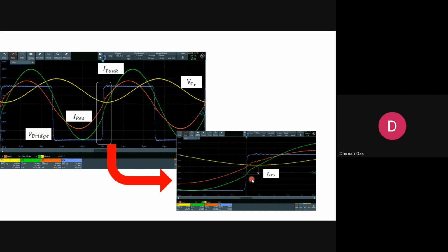You see the amplitude, this negative current reaches zero here. So from here to here, it is charging the output capacitor. Negative current means the current is going towards the switch. This is the natural phenomenon of the converter. You need no extra arrangement, extra commutation, or anything extra.